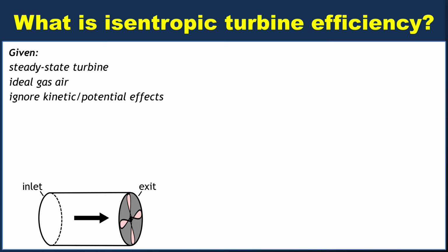Furthermore, we're told that the amount of work produced per m dot, namely W dot over m dot, is 30.3 kilojoules per kilogram. So all we've done is factored out the timing and made it into a mass rate instead of a time rate of energy delivery. Okay, so the turbine is outputting that to its environment.